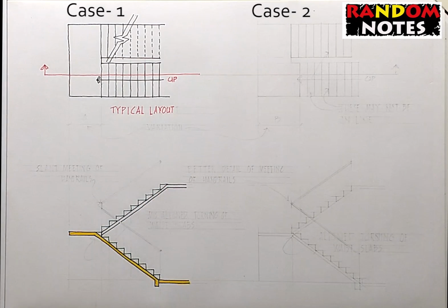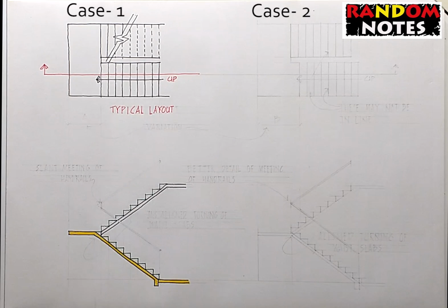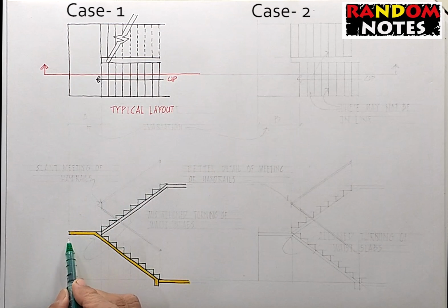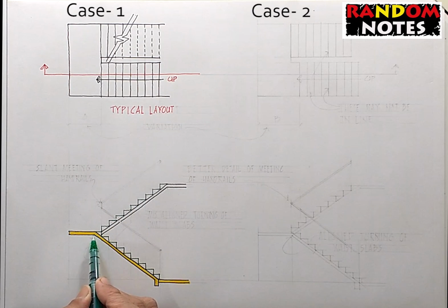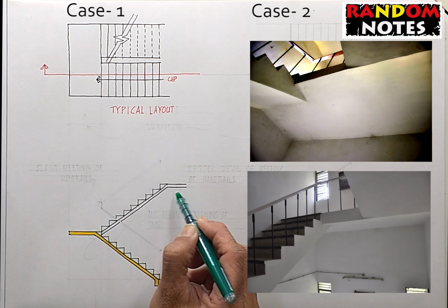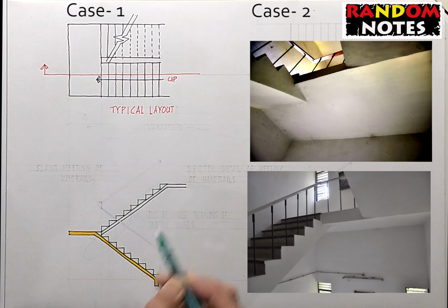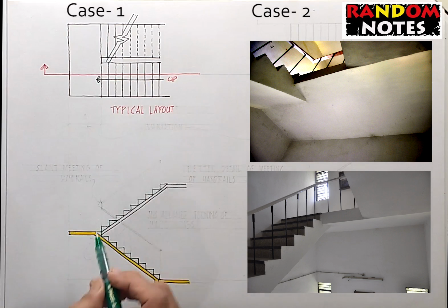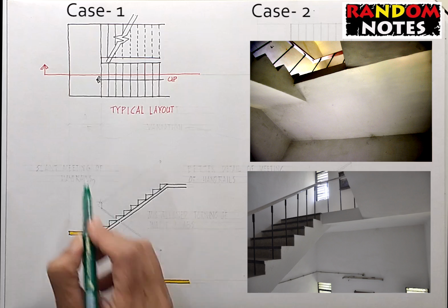Let us now understand a few conditions of the waist slabs meeting the mid landing. Seeing the soffit of the mid landing and the waist slabs, this is where the yellow waist slab turns down to meet the plinth beam. Understanding the turning of the waist slab of the flight rising up from the mid landing, we see that the fold of this second flight starts slightly ahead of the turning of the first waist slab. Thus the turning of the yellow waist slab and the slab beyond are not aligned. You may see mismatched meeting of the mid landing and the two waist slabs. This will give an L shape to the soffit of the mid landing.